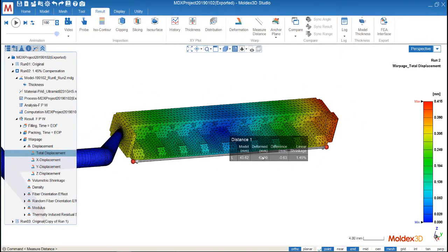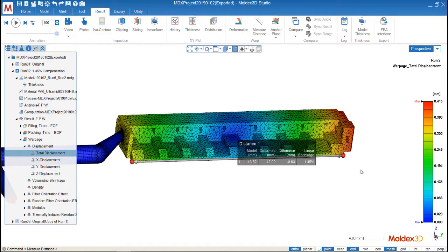to see which is the best linear shrinkage ratio of the part, since for most parts, the compensation does not only come from the material, because there is also the warpage. It's not in-plane shrinkage. Therefore, in this way, you can have something more related to the part geometry, the material, and the process setting for the compensation.